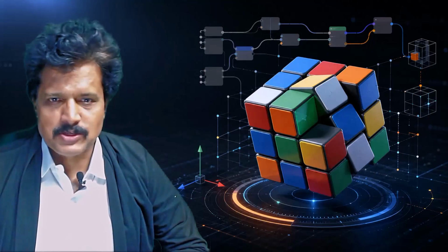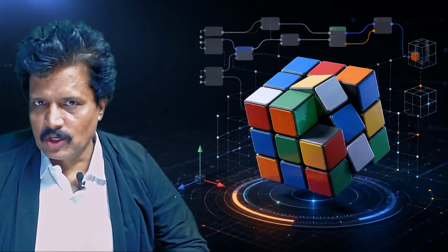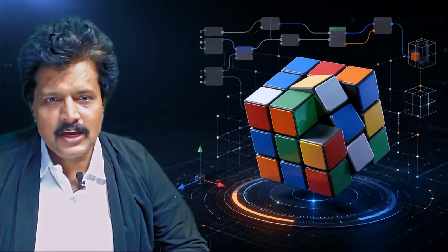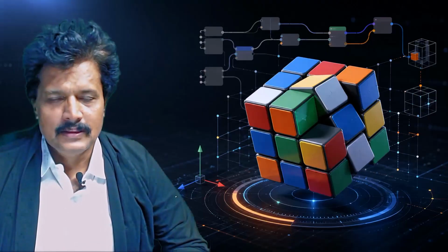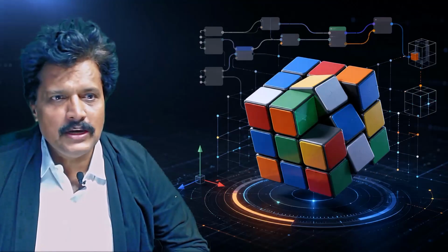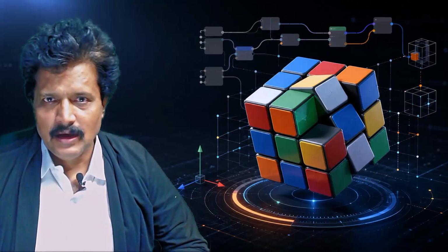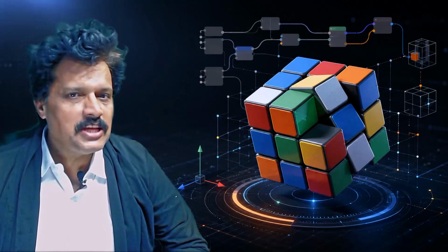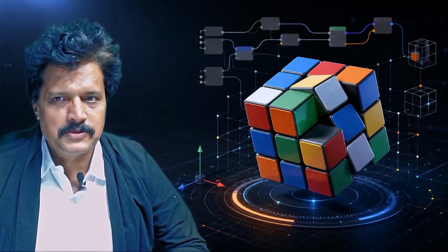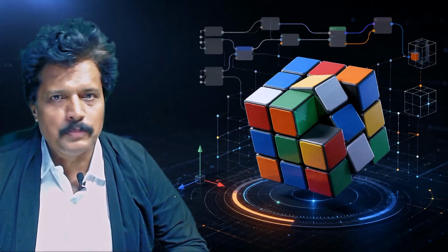In this first episode, we will begin from the default cube in Blender. We will create the cube using geometry nodes. Then we will generate a 3x3x3 structure by using cube vertices as placement points. After that, we will use instance on point to place smaller cubes and form the basic Rubik cube structure.